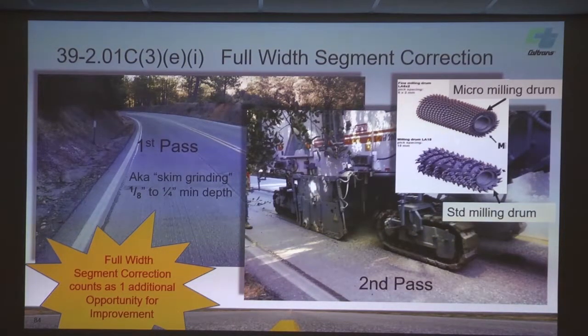It's going to want to adjust the grinder head. The automatics on these cold planers work similar to a paving machine, where you're using an averaging system to smooth things out. It doesn't react as fast as a paver. There are a lot of settings in here, and a lot of these guys will say their software is way better than the other cold planers.